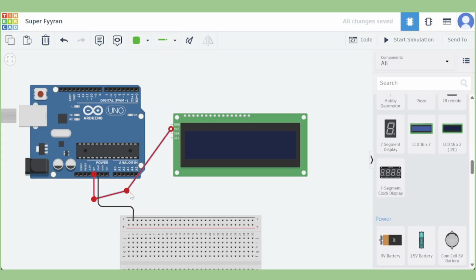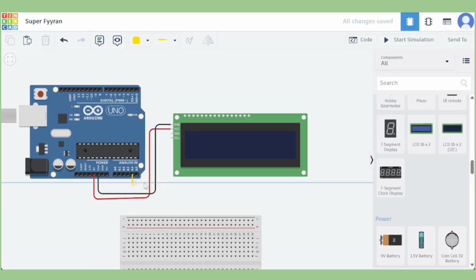Next, I tested the second type of LCD, the I2C model. The library used is LiquidCrystal_I2C. It only has 4 pins, which greatly reduces the installation complexity. Besides VCC and GND, it uses the analog pins A4 and A5.